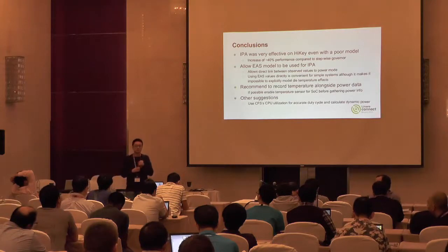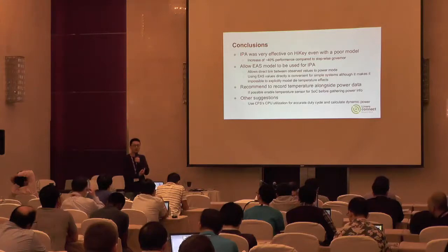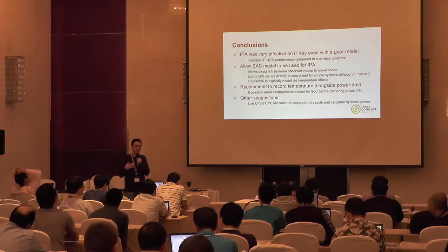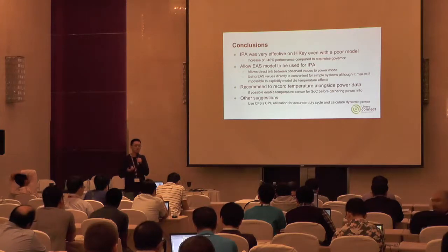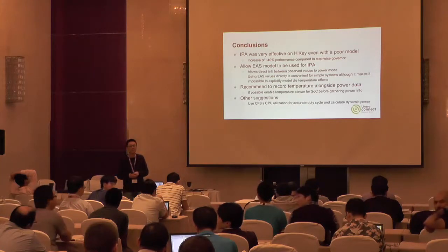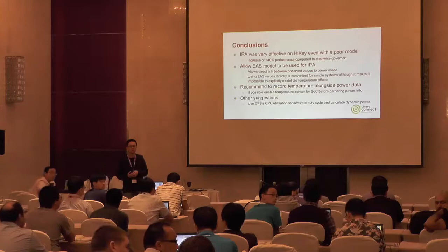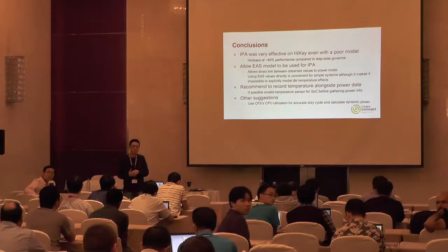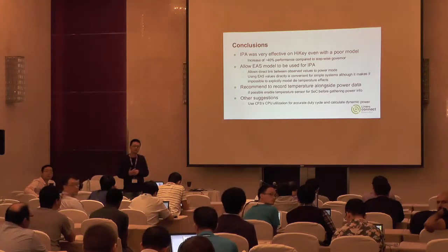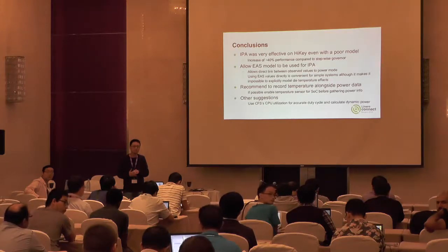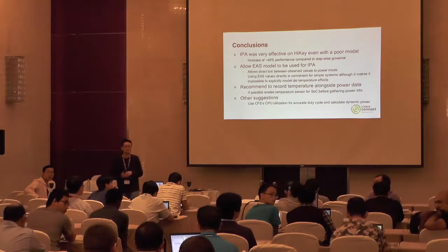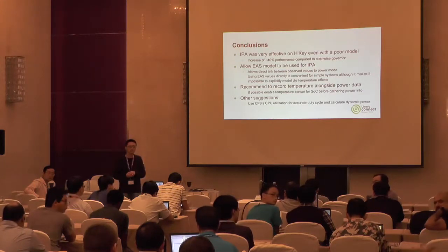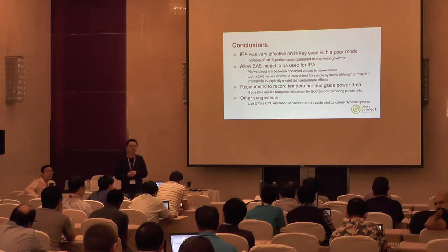Oh yeah. So here I think maybe later, if we integrate with EAS, we can use the scheduler's utilization parameters to get more accurate results. Maybe, because the way this scheduler calculates utilization, it's a geometric series. It's got a decaying function. While for thermal we tend to use the square window. We tried using the scheduler signal, we compared the two signals, and we found that the square window is better for thermal purposes.